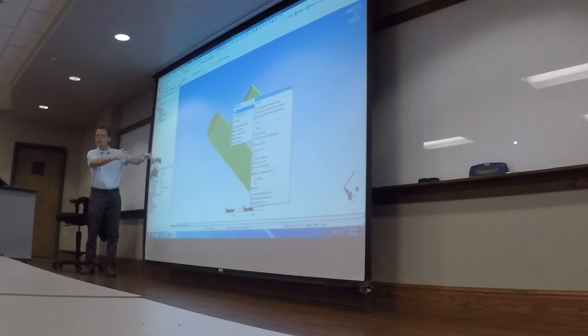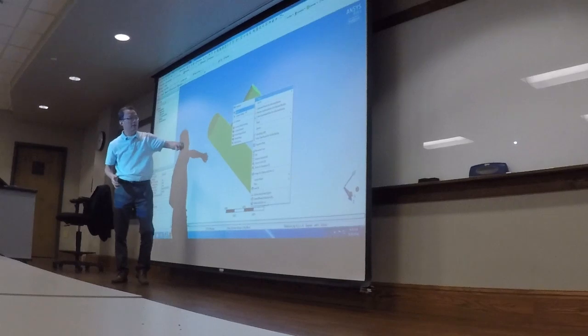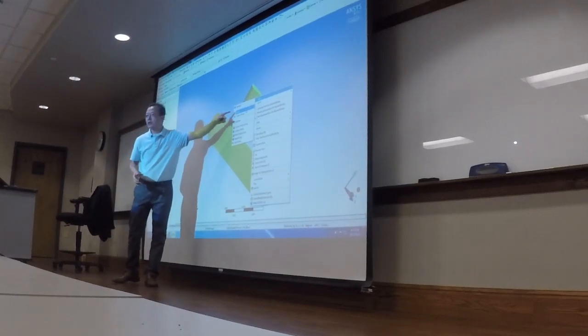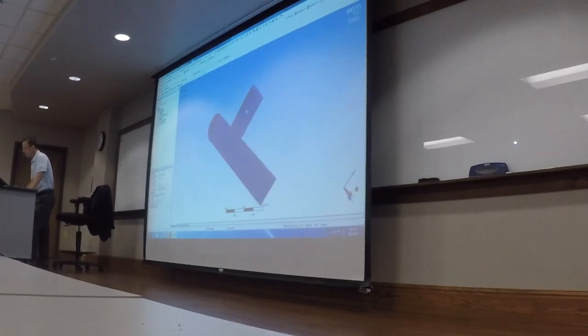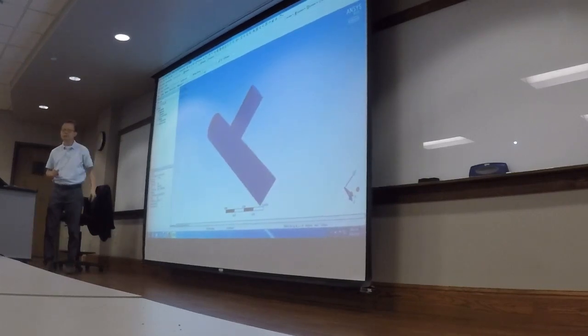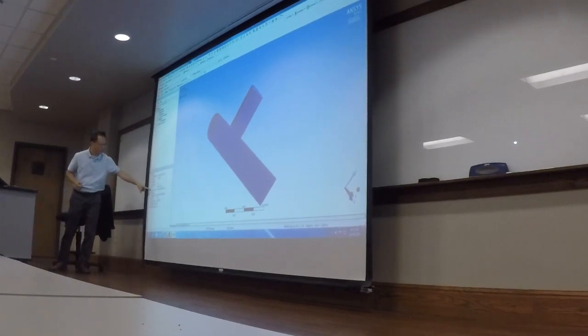So this software understands, oh, you are going to do something to the mesh. You're going to specify a sizing function. Click on the mesh, then select the body. Click on the body, right click, insert sizing. All right. And if everything goes right, you will see the color change. And these are details of the body sizing.